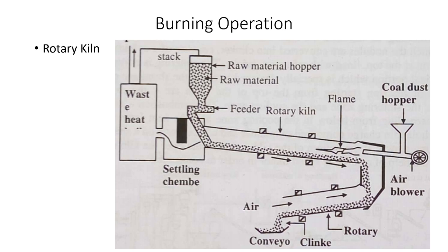Okay, so why is it so? When this cylindrical part of the furnace rotates slowly, the material moves ahead. The rotation speed of this cylinder is from half a rotation per minute to two rotations per minute, or it can rotate 30 times or 60 times per hour.